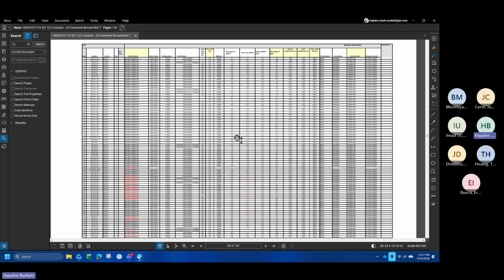That one's set by test and balance, and it's set for a very specific amount of flow. You likely would see three valves in that scenario if that configuration had a 3-way actuator.